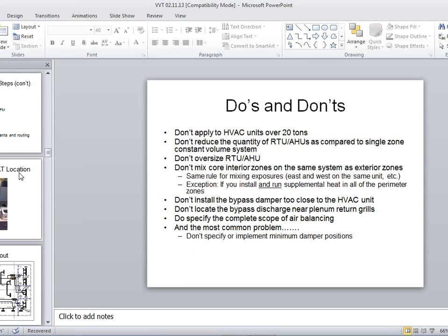Another thing to look for would be if you could get into the ductwork area, if you could see a bypass damper, would be another sign. Or if you see any type of zone controller or sensor in the space that looks like it's not a standard thermostat, that would be another thing that's telling you, hey, you might have a VVT system here. Or if you can trace the wires to the thermostat terminal on the rooftop unit to multiple locations, if it's going to a relay board that's going to different zones, that would be something else that would indicate you have VVT.